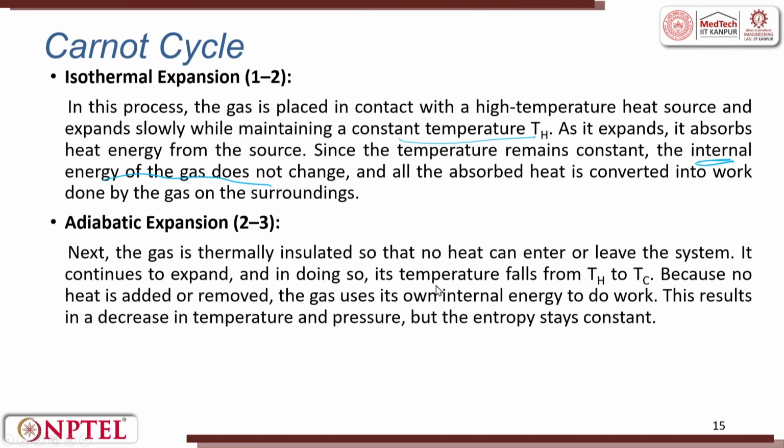2 to 3 there is an adiabatic expansion. Next, the gas is thermally insulated, so no heat can enter or leave the system. It continues to expand and in doing so, its temperature falls from TH to TC because no heat is added or removed. The gas uses its own internal energy for working.